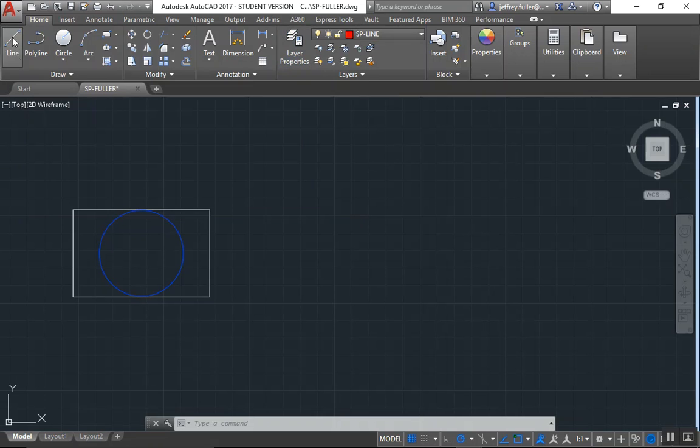The other way to activate a layer is what you just saw me do a few minutes ago, where I went up here to the line drop-down menu and selected the particular layer. All right, so I need to draw this red line. So the same thing with the line. I want to find the exact center of that circle. Sometimes it'll just light up on you, but if not, just go up here and find the midpoint here, and then find the midpoint on the right hand side here, and now it locks right in the middle.